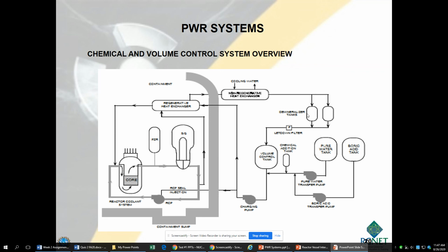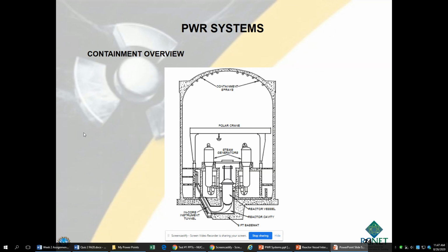And we talked about last time, these demineralizers need cool water. So I'm going to go through these heat exchangers just to cool everything off before it gets to these demineralizers. And then you can see on the way back, it's going to have to go back through this heat exchanger. So that's why it's regenerative. So I'm heating the water back up before it goes into the reactor. And in the act of heating this water up, I'm actually cooling this water off that's on its way back towards the demineralizers.